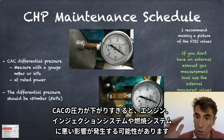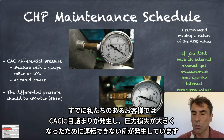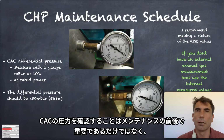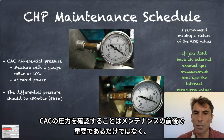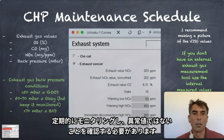If the charge air pressure gets too low, we can get problems with the engine injection or combustion system, as we sometimes already had at the Urimaku plant, where the charge air cooler got blocked, and then we have a high pressure drop and the engine cannot operate in the proper range or in the safe range. It's very important that we always measure that before we do the maintenance, so that we know the status of the charge air cooler and can see where the pressure drop is.